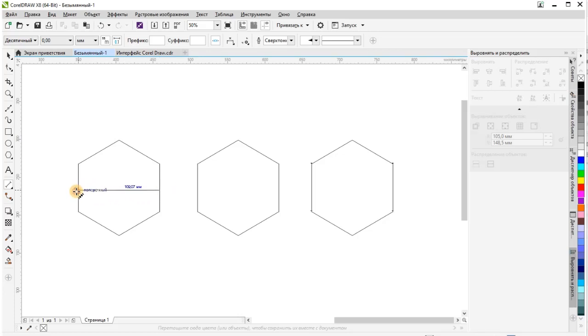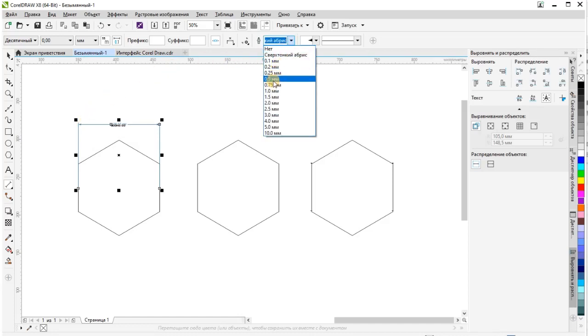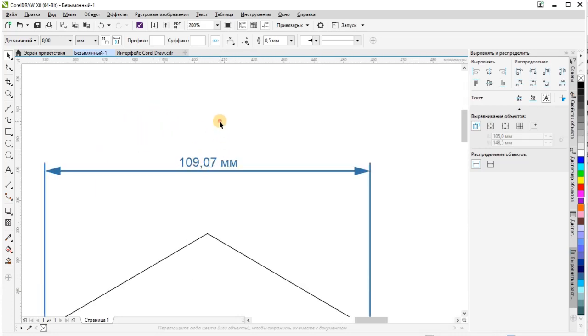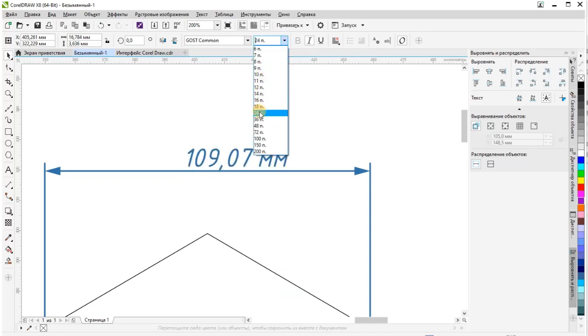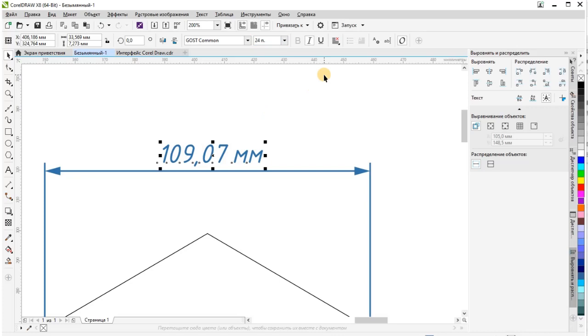Drawing dimension lines. You can draw dimension lines to indicate the distance between 2 points in a drawing or the size of objects. You can add several types of dimension lines. Parallel dimension lines measure the actual distance between 2 nodes. Vertical or horizontal dimension lines measure the vertical y-axis or horizontal x-axis distance between any 2 nodes. Angular dimension lines measure angles.